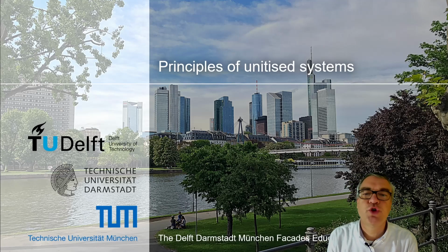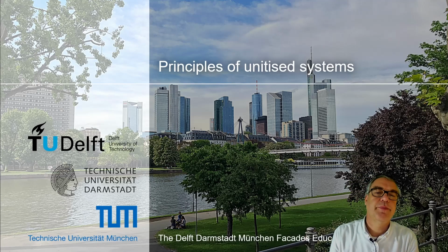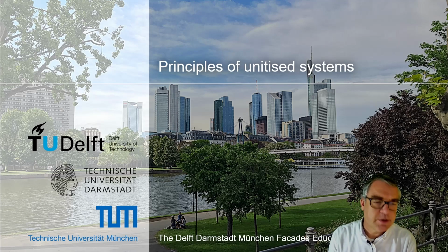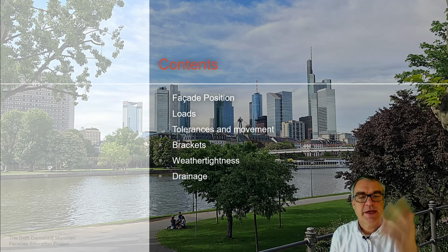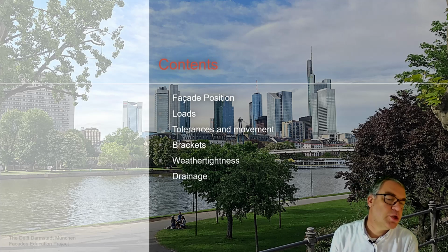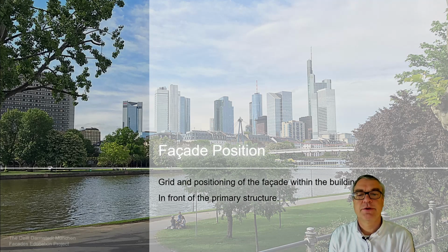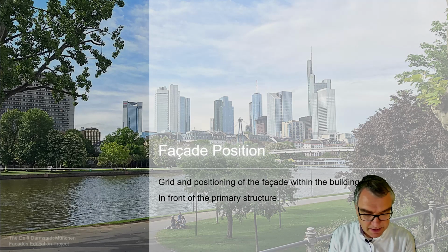Lecture DO2, Principles of Unitized Facade Systems, in comparison to stick systems, unitized systems as an entire frame. And we follow the same outline of the lecture: the positioning of the facade, the loads of the facade, tolerances and movements and how to deal with that, the brackets which do deal with the tolerance and movement, the water tightness and result of the water tightness, the drainage of this system.